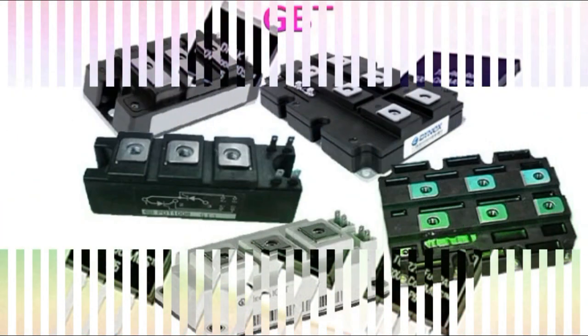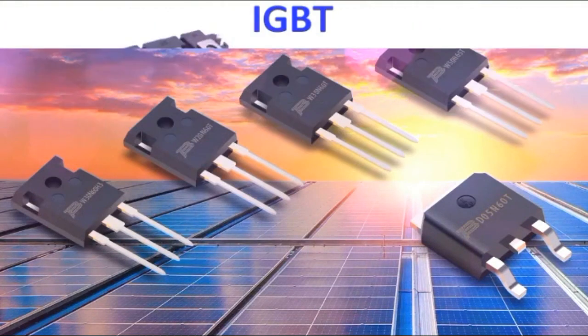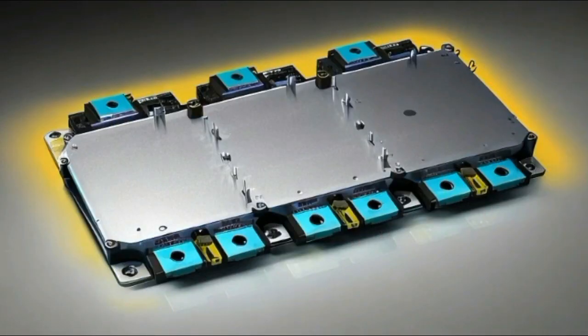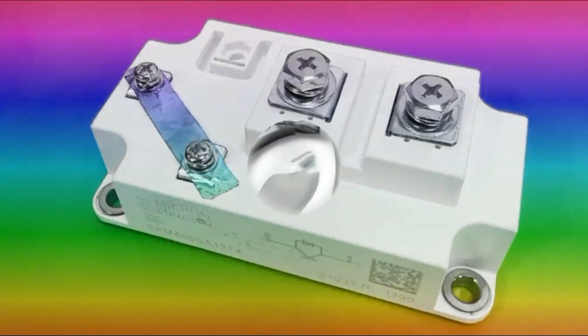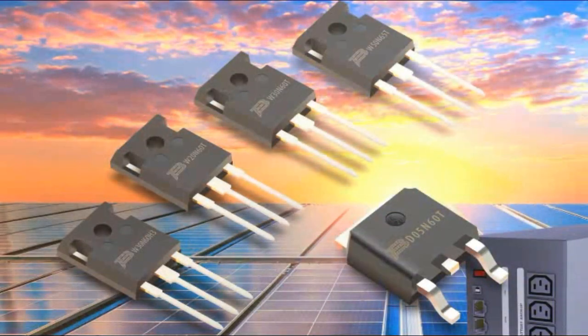In conclusion, it can be said that the main advantage of using an IGBT over other transistors is the ability to work at high voltage, low on-state resistance, simple setup, relatively high switching speed, and zero gate startup current, which makes them a good choice for high voltage applications such as modulation, pulse width modulation (PWM), variable speed control, switching power supplies, solar DC-AC inverters, and frequency converter applications in the several thousand kHz range.